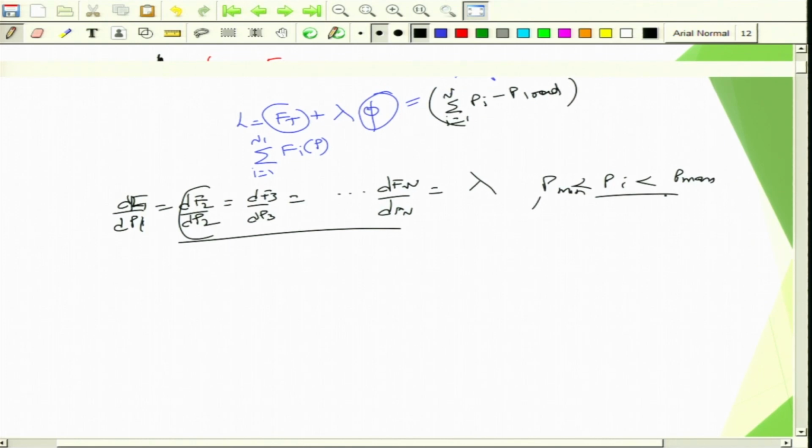Once these limits have been imposed, we need to ensure that a given combination of generator outputs, which comes out as an optimal lambda, does not go lower than the minimum or beyond the maximum. If it touches a threshold, then we assign that threshold to that specific generator.